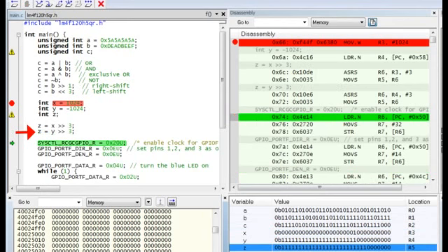However, the right shift of the negative value y behaves completely differently than before, because now ones are shifted into the most significant bit. So you've just found out that right shifting of a signed integer shifts zeros into the most significant bit when the bit is 0 before the shift, and ones when the bit is 1 before the shift. This is called sign extending of a negative value in the 2's complement representation, which you learned in lesson 1. This sign extending is necessary to preserve the correspondence between right shifting and division by a power of 2.